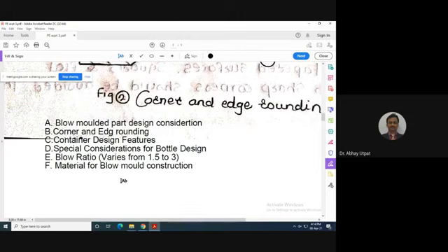Apart from aluminum and beryllium, the strength of steel is better than aluminum. That's why steel is preferred many times. And apart from it, some zinc alloys can also be used for preparing the molds. Zinc also has good thermal conductivity, and synthetic plastics such as acrylic polyesters can also be used. Here miscellaneous material includes zinc materials, but other than that, steel, copper beryllium, and aluminum alloys.